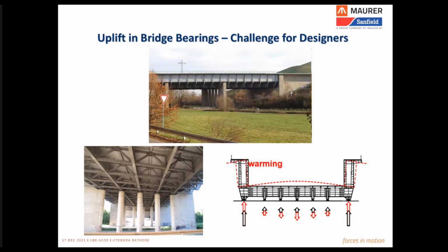The next challenge for bridge designers to handle in bridge bearings is uplift. If we talk about standard single span structures, the requirement of uplift is generally not there. But when we talk about structures which are continuous, or structures which are curved, then for such structures, under certain conditions of loading, the bearings which are installed on the outer part or at the extreme abutment locations may experience, in addition to the gravity loads, sometimes tension loads also.